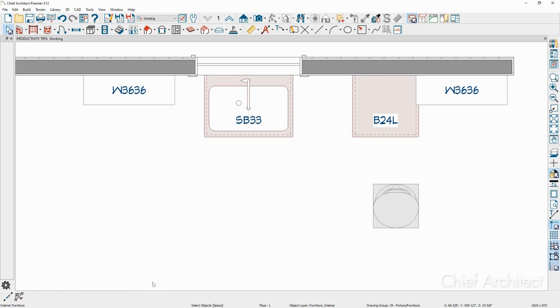In the sub edit menu that comes up, far left hand corner of my screen, is the tool point to point center. When I click this tool and I click on this cabinet and this cabinet, it projects 2 points that I can actually center that stool on. Now I haven't clicked anything, but it's projecting 2 CAD points.